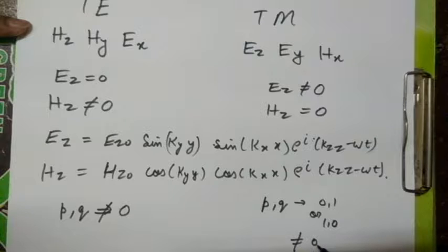Here TE and TM modes are represented as TEpq and TMpq, where pq represents the integers discussed above, and it also means that the size associated with p, that is b, is longer than a. The lowest mode is called the dominant mode in both TE and TM. TE modes have Hz, Hy and Ex, while TM modes have Ez, Ey and Hx.